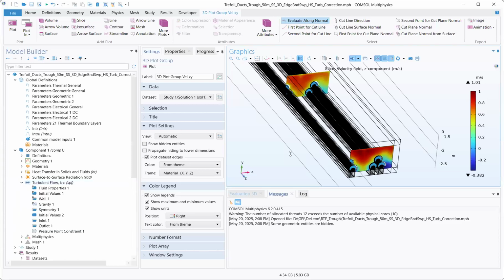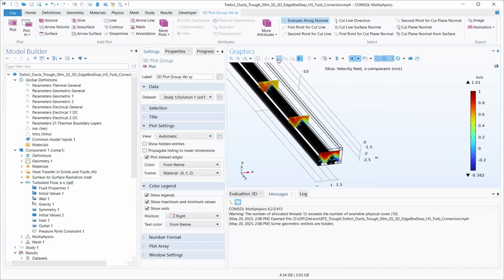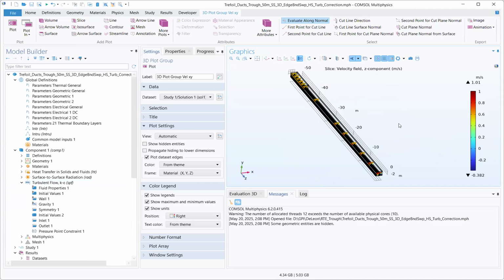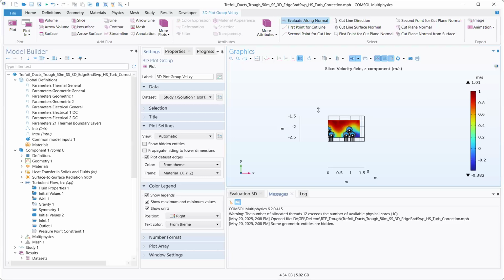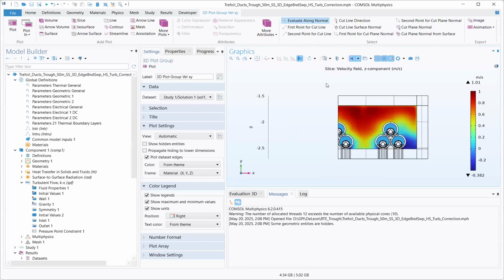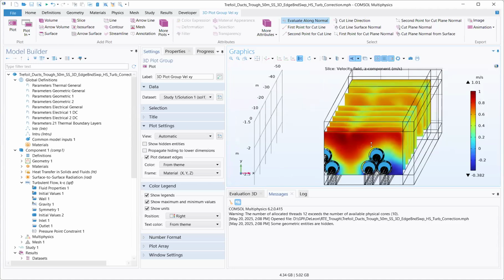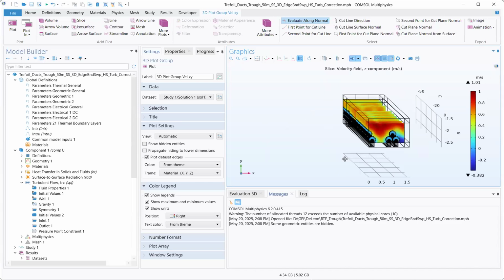Okay. One thing to mention: what are the complications in modeling this, different from the other things you have shown? What would be a particularity that somebody would need to know to do this? Okay, so this is a 3D model, so a large project, large file. In this case, we take advantage of symmetry along the YZ plane, so we cut it in half, and that reduces the size by at least half.